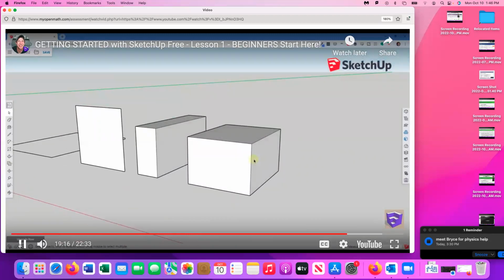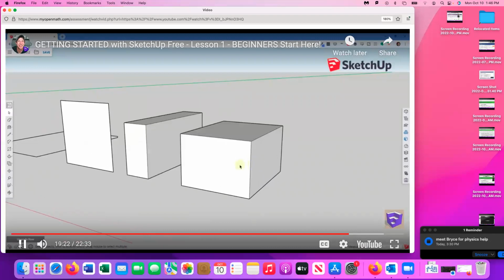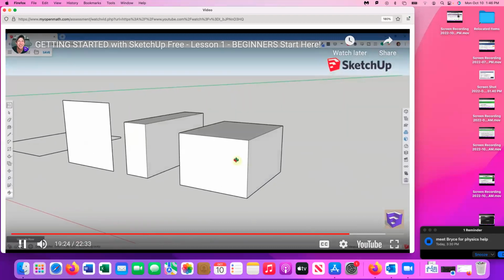So you're going to use the push-pull tool a lot in order to create different 3D things. Not only can you use the push-pull tool to add material, you can also use it to remove material. Let's say, for example, that I drew an arc across this edge right here. You can see how I split this face into 2 different faces.